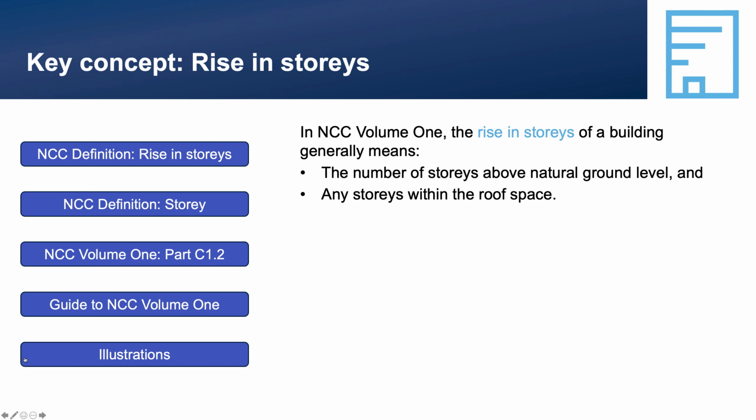For example, it is central to identifying which rules apply when ensuring that a building can resist fire appropriately. A number of concessions around fire resistance provisions depend in part on the building's rise in stories. This means that some provisions may not apply to a building below a certain rise in stories, provided other conditions are met. For example, C 3.7 protection of doorways in horizontal exits, and C 3.10 openings in fire isolated lift shafts.